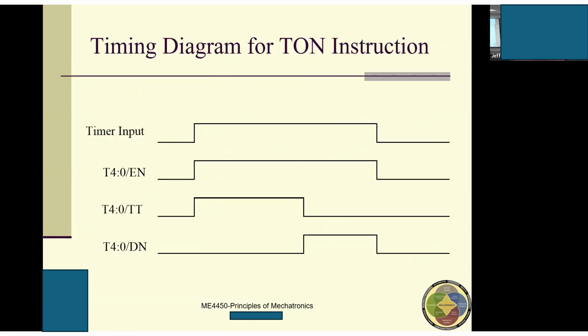Here is a time diagram for this TON instruction. Here is the time, and when the time is done, the done bit is set, and it stays set until the enable becomes false.